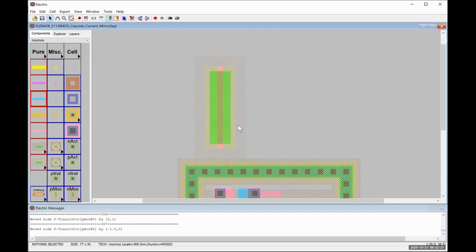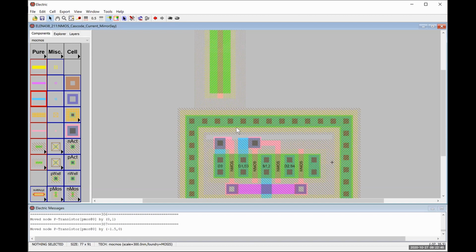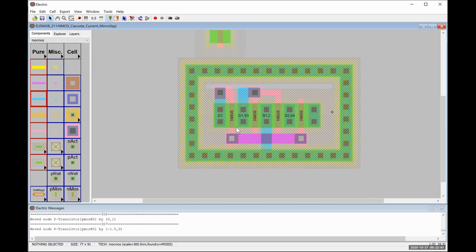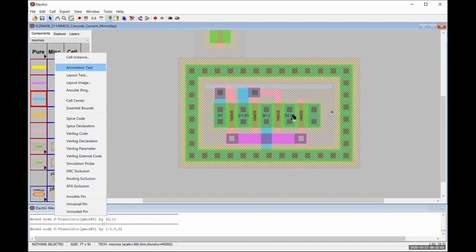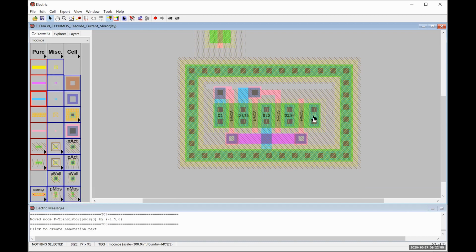We're going to need to do a body connection for that guy. So what I'm considering here, right now this is a 30 by 2, but what I'm considering doing is 3 10 by 2s in parallel so that it'll more closely match the physical dimensions of our 4 transistors here on the bottom. Where, just to be clear, I never did this guy.